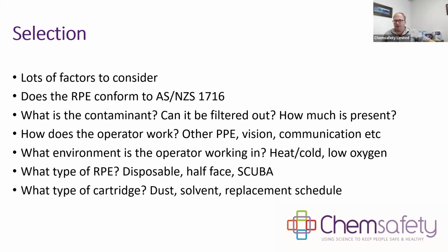At any point, if you smell anything through the solvent-based filter, it should be replaced. That's a key giveaway, but you ideally want to stop. If you're smelling it, you've been exposed to it, so you want to stop that before that happens.